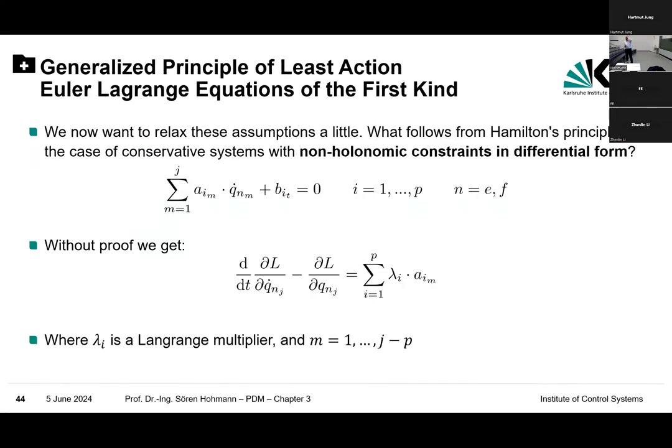Okay, so, and here a short glimpse on systems which do not have just holonomic constraints, but non-holonomic constraints. It's possible to include them. And if you remember, the non-holonomic constraints are split into two parts. The ones which are governed by relations, so inequalities, for example, and the ones which are derivative non-holonomic constraints, which are a little bit strangely defined, meaning first saying, well, these are those constraints which can't be fit in an algebraic relation. These can be treated in this Euler-Lagrange formalism very easily.